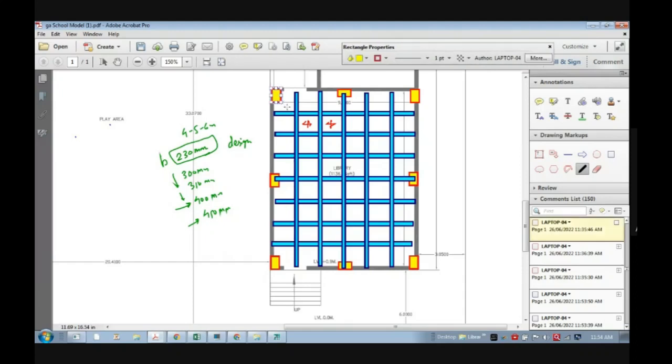So try to understand, this is a two-way slab, and all of you know that two-way slab is having a triangular distribution like this. ऐसे ही रहेगा ना इसका distribution. And trapezoidal distribution, right? So the load will transfer like this only. We will have a beam at the boundary, all boundary pe beam bhi hai, and the load distribution. So I can say that this 9 meter by 12 meter slab, I have done the stiffening at intermediate levels.